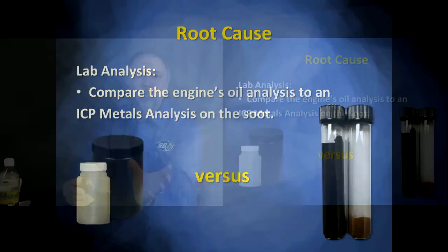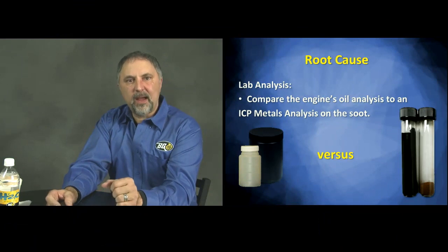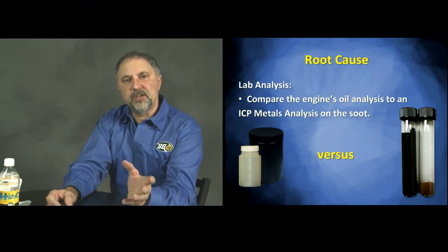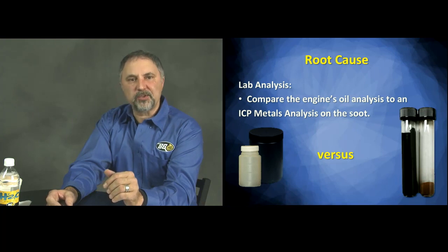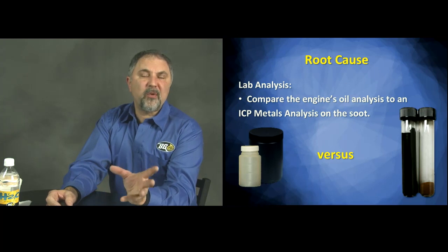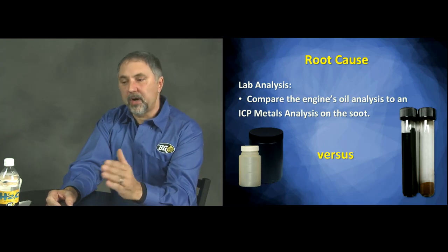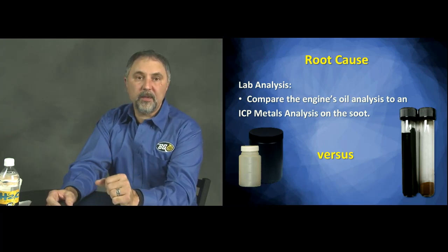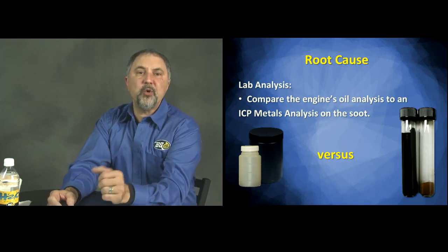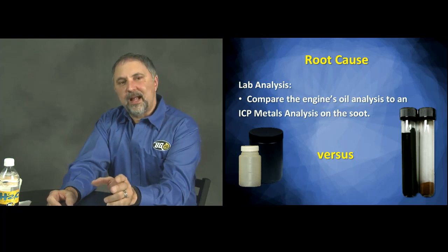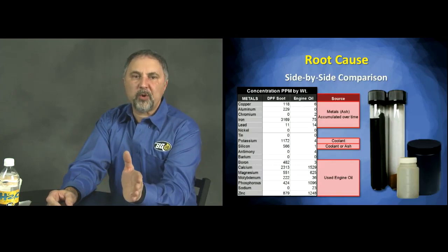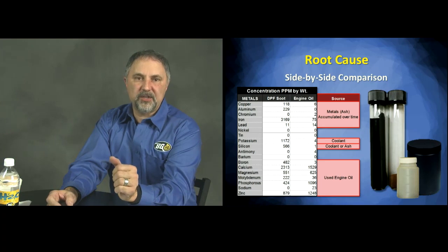Take that soot with the oil, send it to the lab, and have them perform an analysis on the soot. That analysis is called an ICP metals analysis. Now, unfortunately, I don't think Polaris performs that test, but I know our guys here in Wichita do. Shane and Dustin will oversee that, and Don and Mike. We do have this ability to perform the ICP metals analysis. The ICP metals analysis will actually give you a report that looks very similar to an oil analysis.